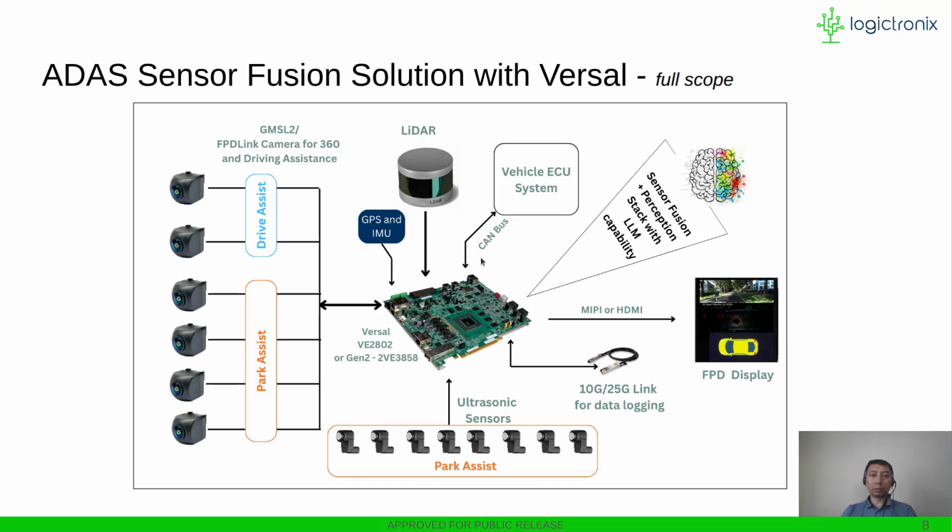We also have CAN running on this platform for communicating with the ECU system of the vehicle. For visualizing the output, we are using an HDMI based display for displaying all the sensor, LiDAR, or ML related outputs. We also have a 10 gig Ethernet interface for logging and debugging the sensor data.